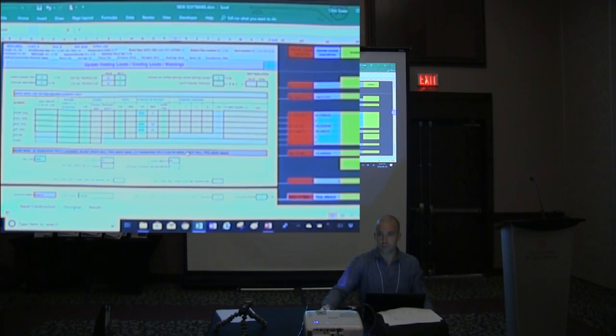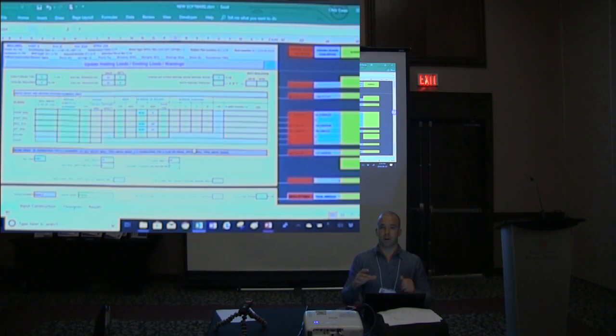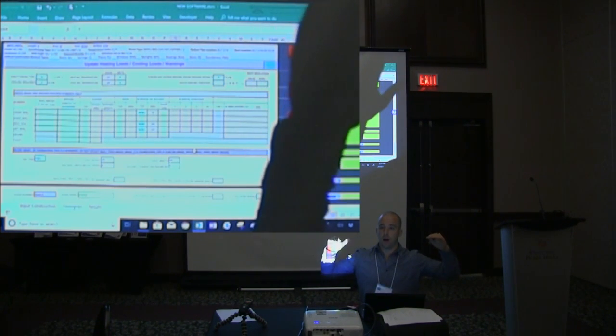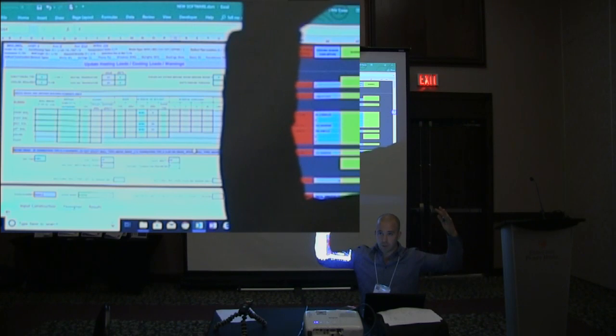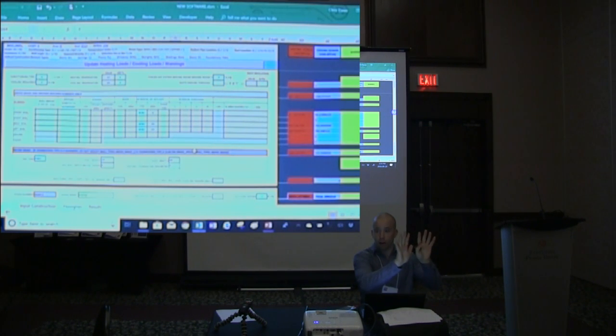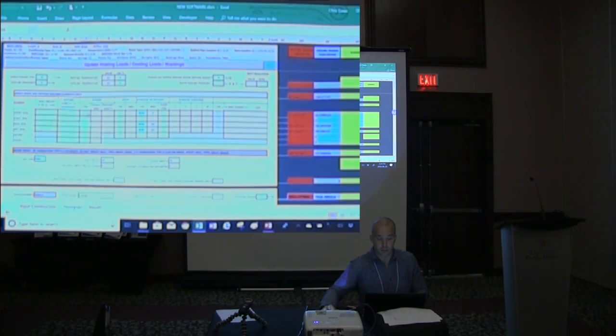With the other basement wall that's not foundation, yeah, so this came up recently. Basically, the below grade is for an element below grade. If you've got a concrete foundation wall coming up a foot above grade and framing on top of that, the framed wall is an element above grade. So you would specify in here whatever framing you have above grade. Yeah. And in the case you're talking about, it would have inputs for foundation and inputs for above grade, because that wall is above grade.